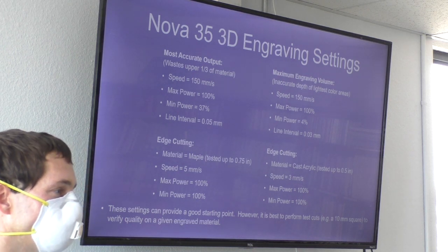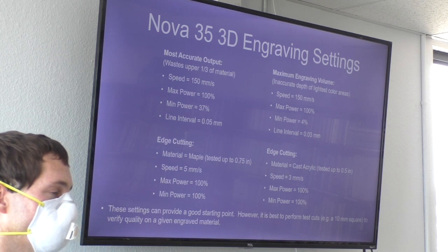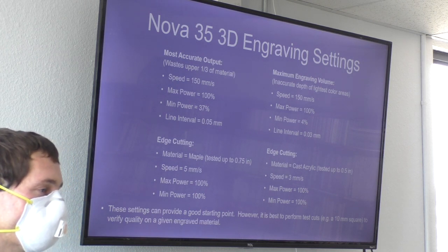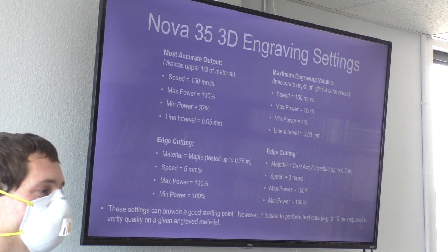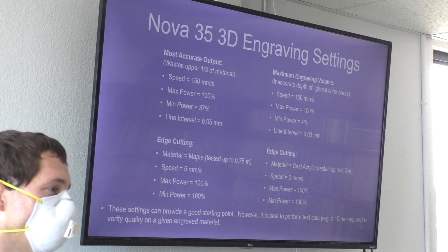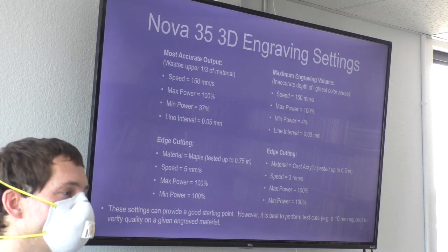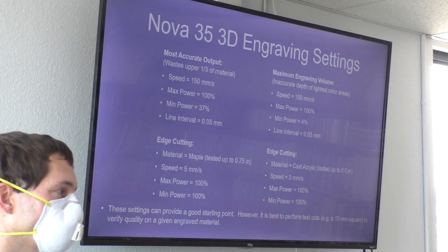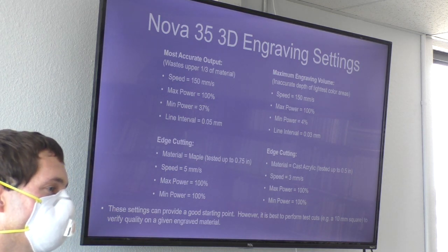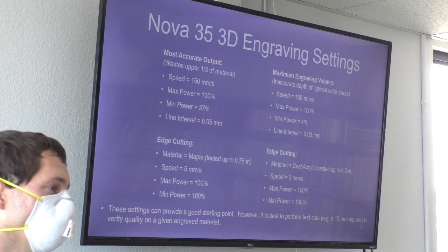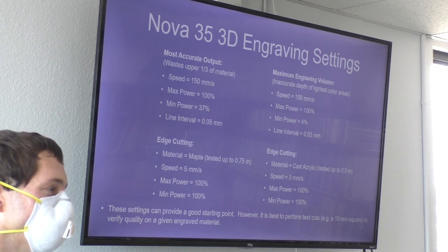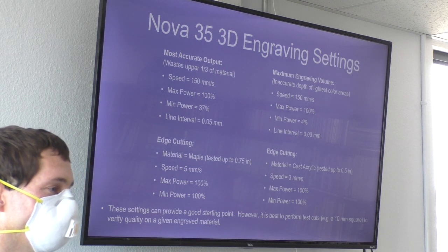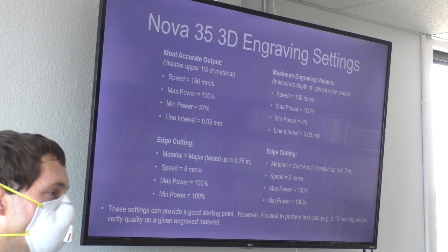Factoring into my material selection enough material that I wasn't trying to go cheap, so that I had stuff to play with, is a critical factor. If I want to get as cheap as possible, and I need a piece that's, say, 3 by 5 inches, so I go buy something that's 3.5 by 5.5 inches, well, now I can't test anything with the material. So if we're ever buying material, that's important.